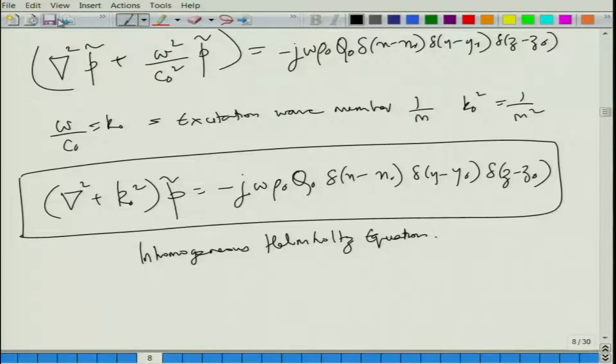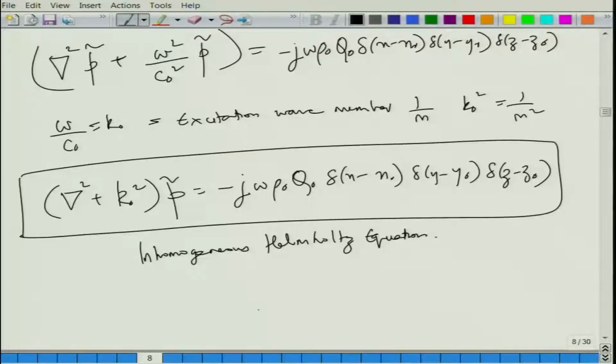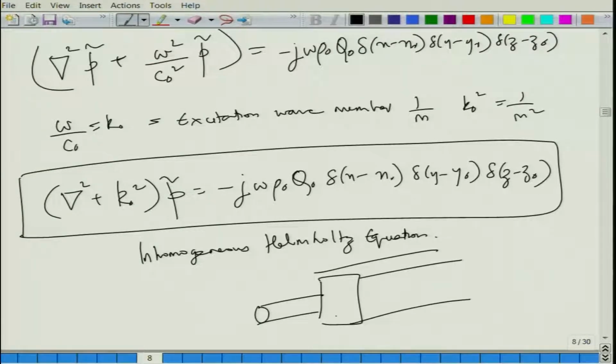It means that, like I said, the source is localized at a particular point. Let us consider a rectangular chamber muffler, where the inlet port is like this, and this is just a rough figure. You have a chamber something like this, and you are trying to squeeze the entire finite area into one point. As if the inlet or the outlet ports are condensed down to a single point, the point of singularity, and that is what is represented by the Dirac delta function.